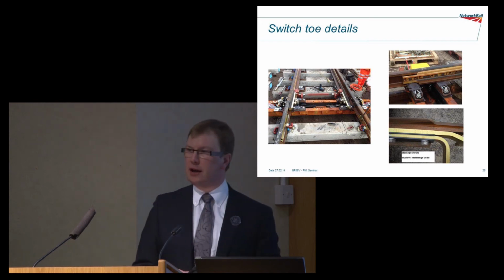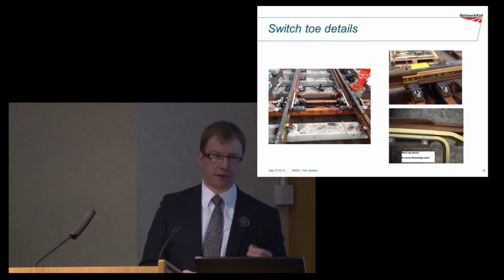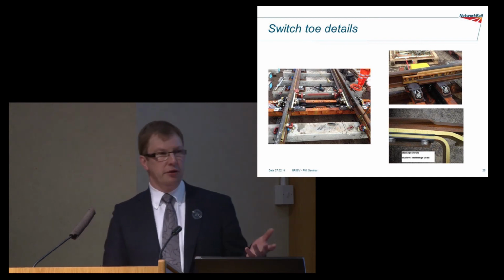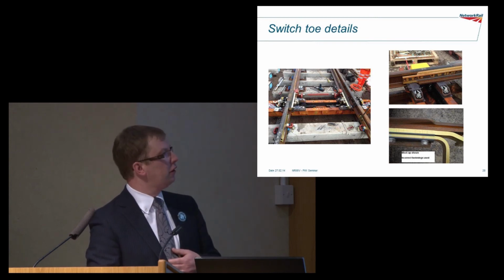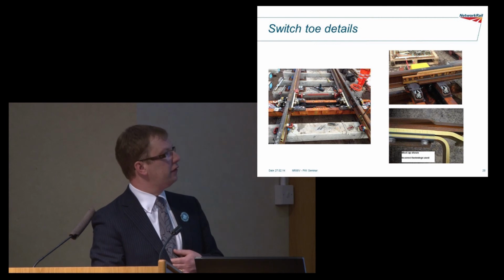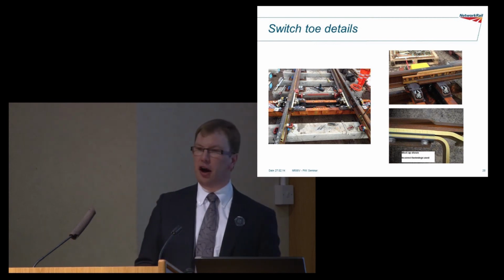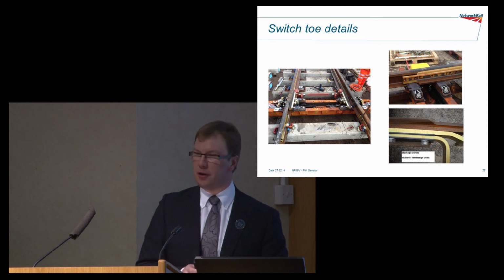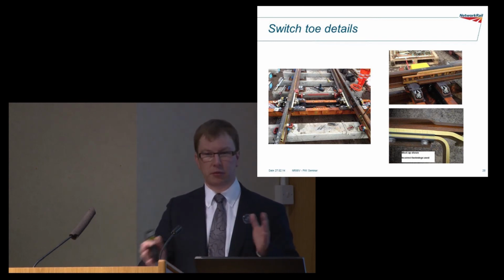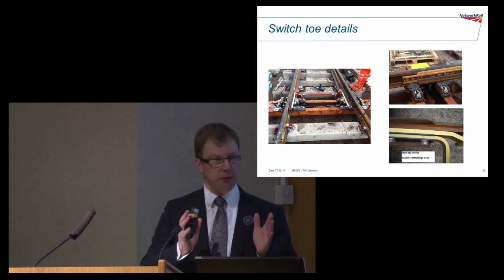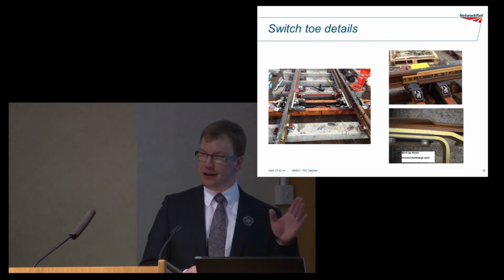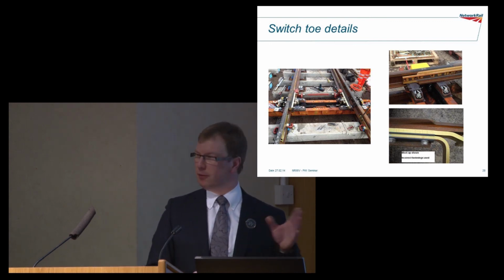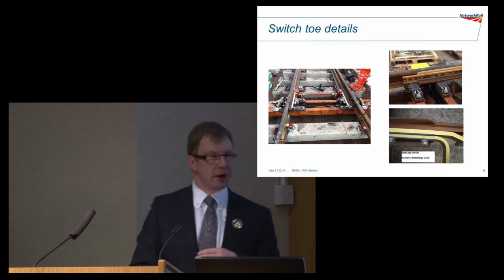This was introduced when in-bearer clamp lock was introduced, and for a short time we had, again, two standards of switches. We had switches for in-bearer clamp lock with the extension, and we had traditional switches that effectively finished there. And again, imagine the half set, just like the crossing, turns up on the night, Saturday night, we're going to put it in, somebody's ordered the wrong one. So we set out a few years ago, let's get one standard. Now this is why people think it's the wrong one, because it does actually work with different POE systems, but it doesn't always look like it will.